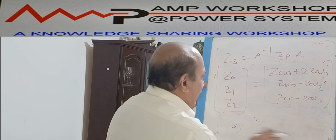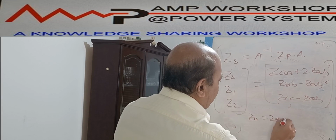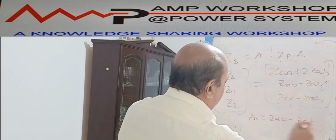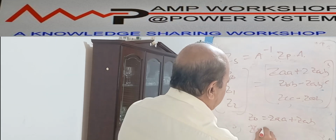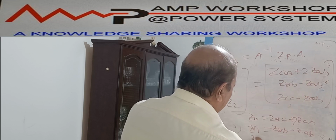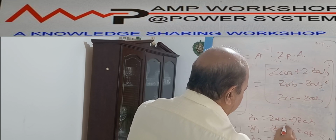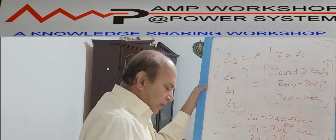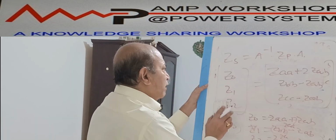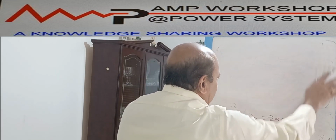Balanced symmetrical transmission line. From this equation you can see Z0 equal to how much? ZAA plus 2ZAB. And Z1 is equal to positive sequence impedance equal to ZBB minus ZAB. And Z2 is equal to ZCC minus ZAB. Now again it is equal, so it will be ZAA. This is also ZAA. Okay, these will be the three sequence impedance. So what will be the corresponding sequence network? Very simple. So we can draw the sequence network for this transmission line.